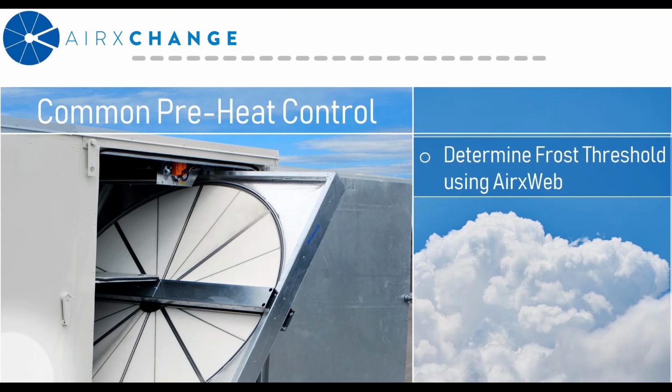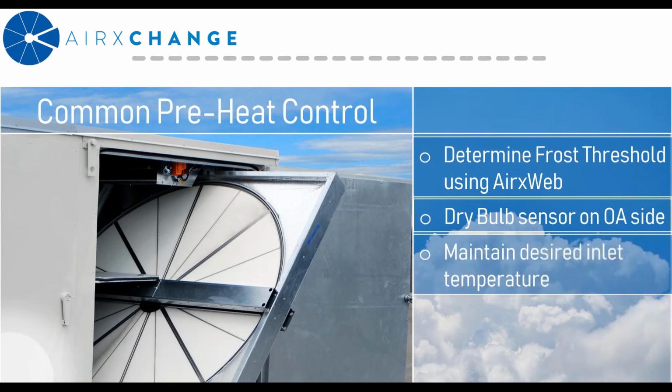Once again, the easiest way to calculate that is to use the Airxchange design software, AirXWeb. After entering the design conditions in the software, it'll tell you what the control point is and the size of the heater required to maintain that inlet temperature. You would then use a dry bulb sensor to monitor the outside air temperature entering the wheel. And if that temperature drops below the frost threshold control point, you would turn the heater on and modulate to maintain that predetermined inlet temperature. Pretty simple system.